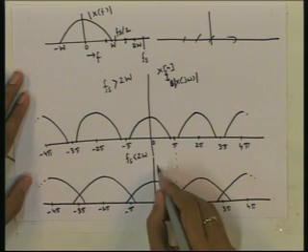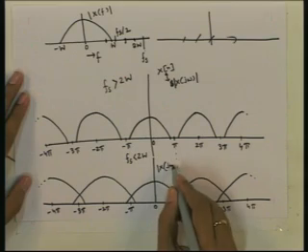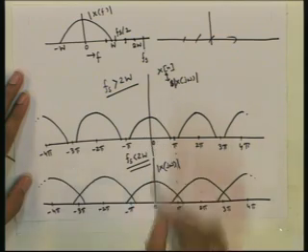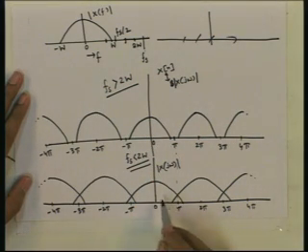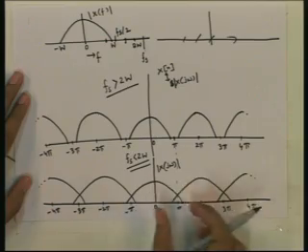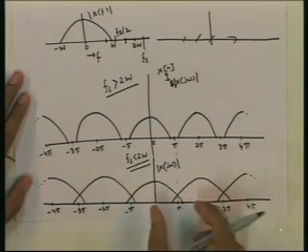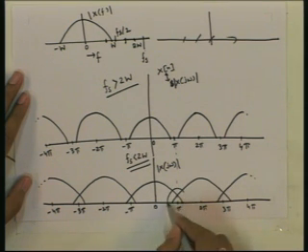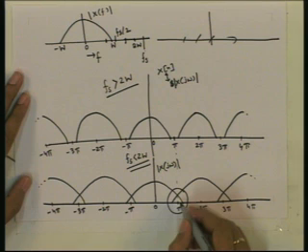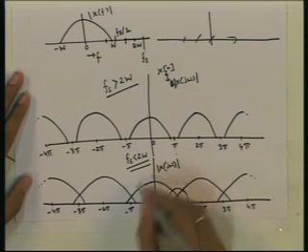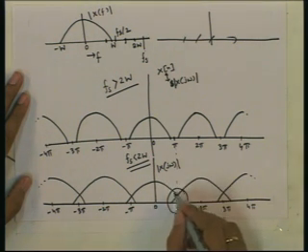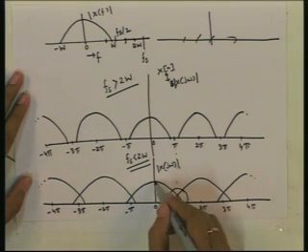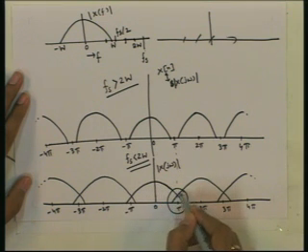So this will be the magnitude of X(j omega) for Fs less than 2W, and this is for Fs greater than 2W. And we see that here there is some mixing between different copies of the original spectrum. So in this part there is some mix up, and what we get is actually the sum of these two components here. The spectrum will look like this, and then something here which is the sum of these.